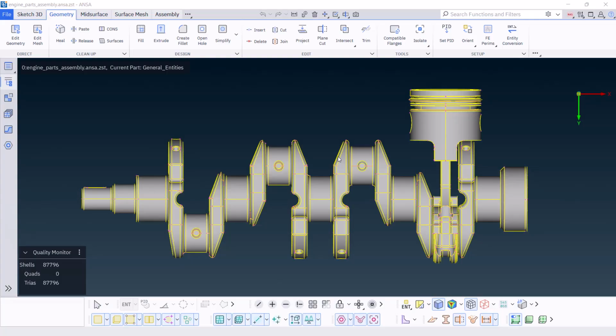Welcome. This video will demonstrate how to use the Connection Manager to manage bolt connections in ANSYS. Since in an assembled model the individual components are connected in various positions and with various techniques, the tools which will carry out such tasks must be able to easily interpret the information provided by the user into the desired FE representations. One of the tools used in ANSYS for this purpose is the Connection Manager.